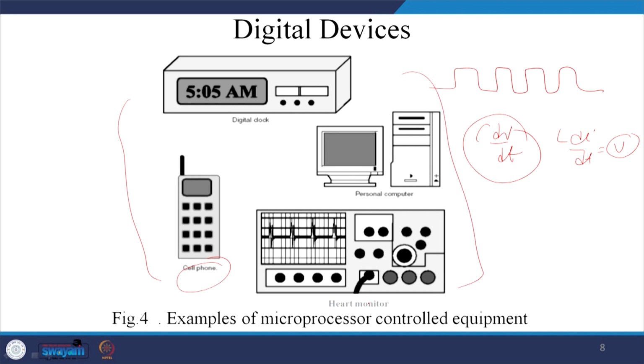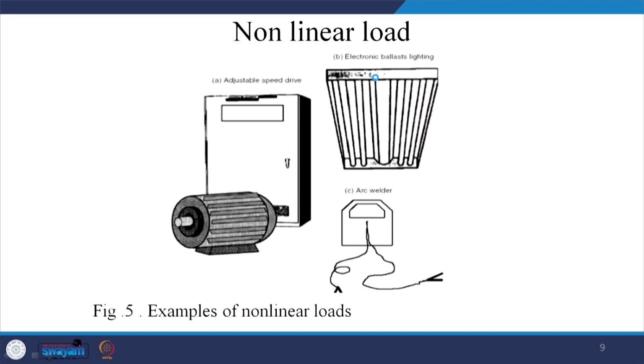All those digital equipments are essentially required to convert AC to DC, and thereafter there will be a chopped DC. Once you convert AC to DC, since it is a nonlinear conversion, you have problems with harmonics, and you thereafter make a pulsation kind of entities, and that leads to more EMI/EMC noise. And this is an example of a nonlinear load.